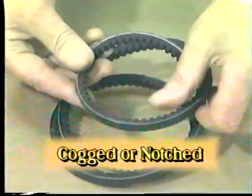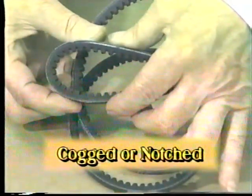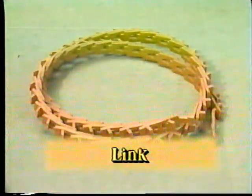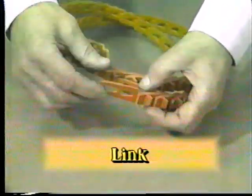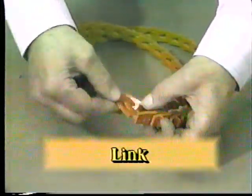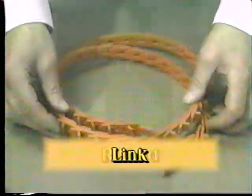Cogged or notched belts permit easy bending and tight turns around small sheaves. They usually have raw edges to give them extra gripping power on the sheave. The link belt is made of individual links, which can usually be replaced without having to alter the center distance between the driver and the driven units. And if a belt is damaged, single sections of the belt can be removed and replaced easily.